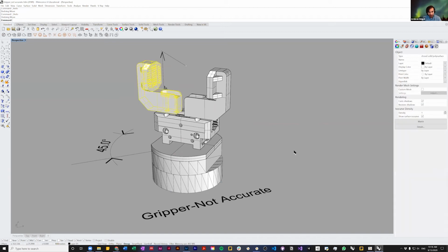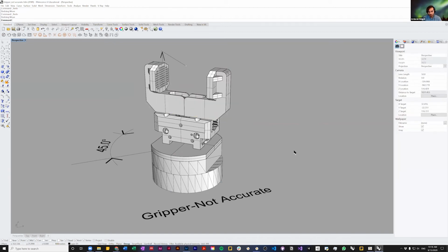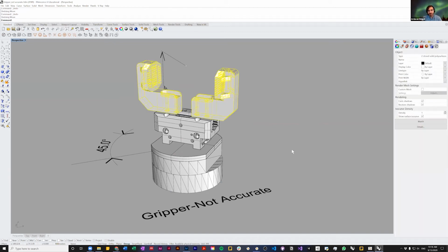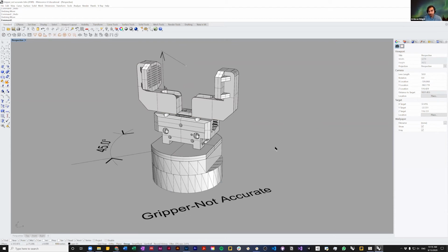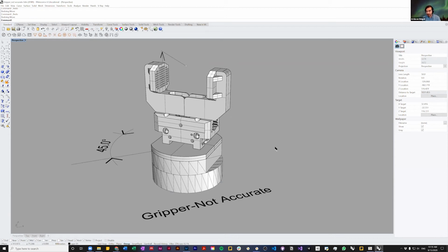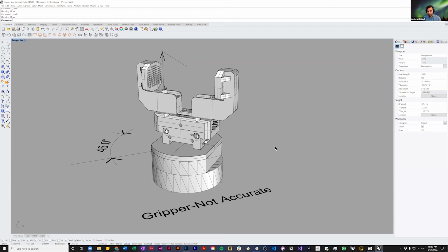So how can we do this? How can we have a tool that has this mechanical action? We need to introduce this tool as a mechanism. And mechanism means that it's an object that has special poses that can switch between them. So in this case, we have a gripper that can do a closed pose or position and an open position or pose. So we need to somehow define this in Robot Studio in that way.